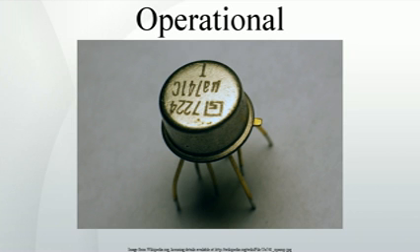Applicability considerations. Note: while the 741 was historically used in audio and other sensitive equipment, such use is now rare because of the improved noise performance of more modern op-amps. Apart from generating noticeable hiss, 741s and other older op-amps may have poor common mode rejection ratios and so will often introduce cable-borne mains hum and other common mode interference, such as switch clicks, into sensitive equipment.